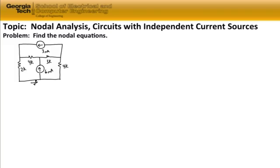So we're going to use nodal analysis, which means that the first step in our process is to identify the nodes and then write the nodal equations about each one of those nodes using Kirchhoff's current law. So let's do that. The first step is to find the nodes. We have node 1, node 2, and node 3, to identify the top nodes, and then we have a ground node, which is a reference node, the 0-volt node at the bottom of the circuit.